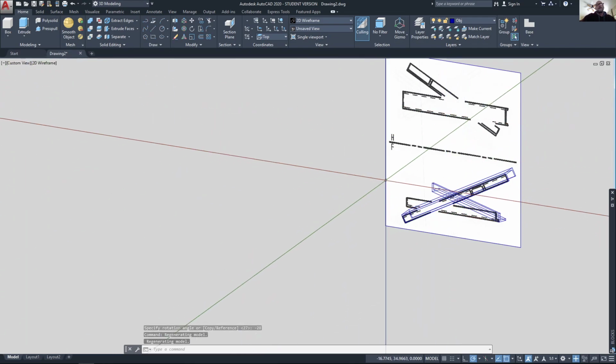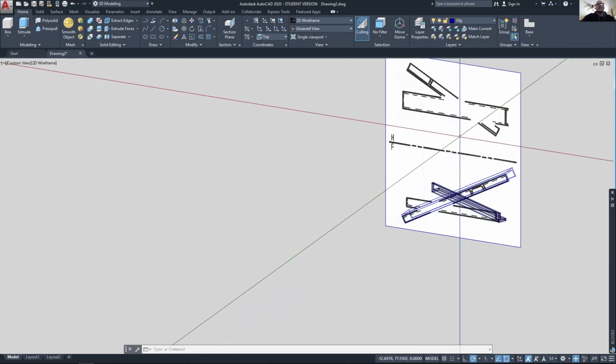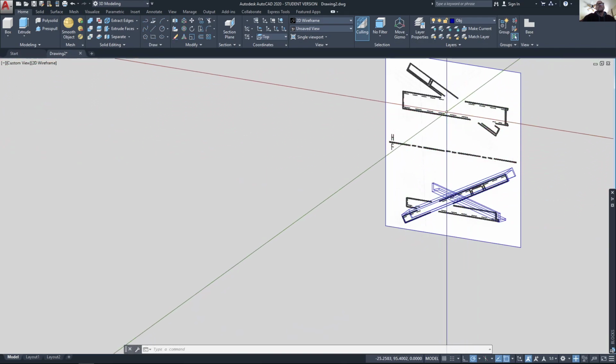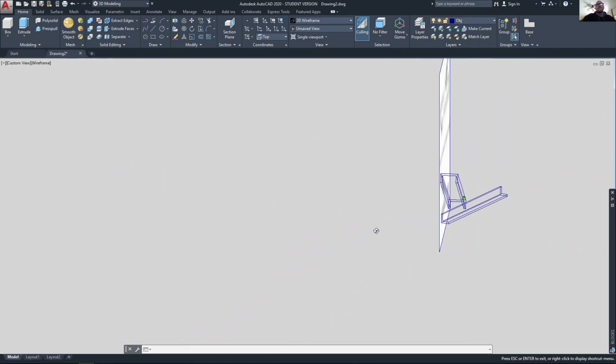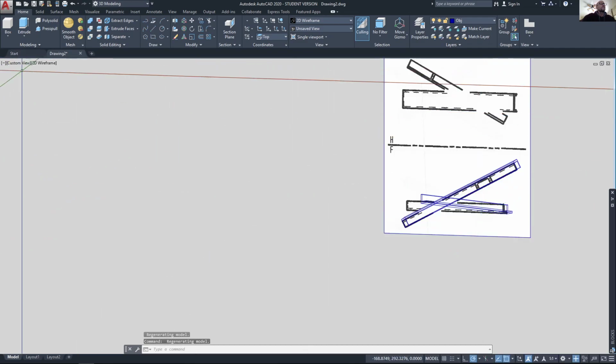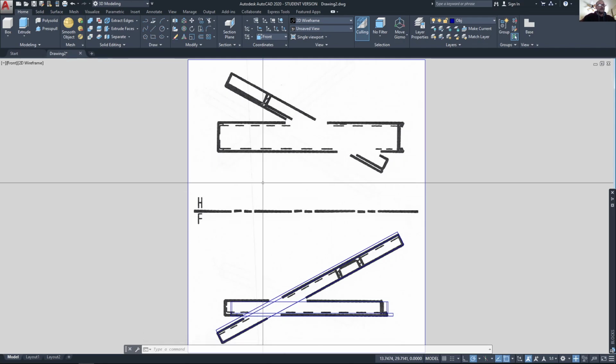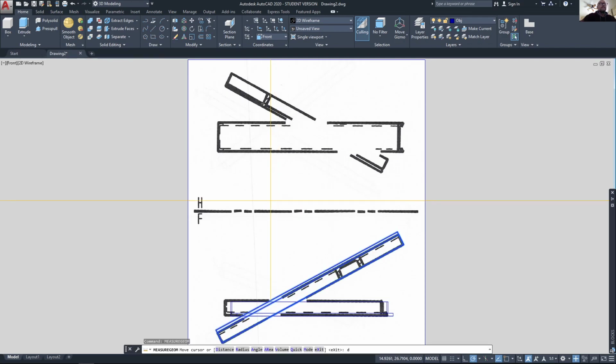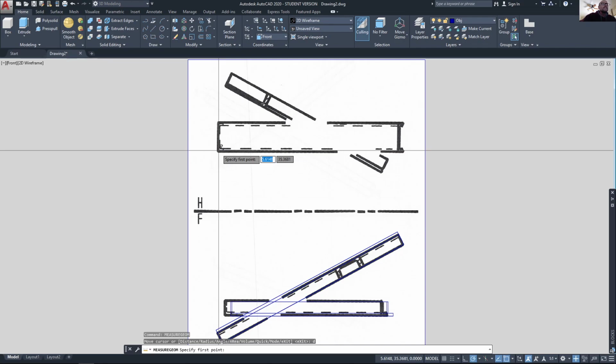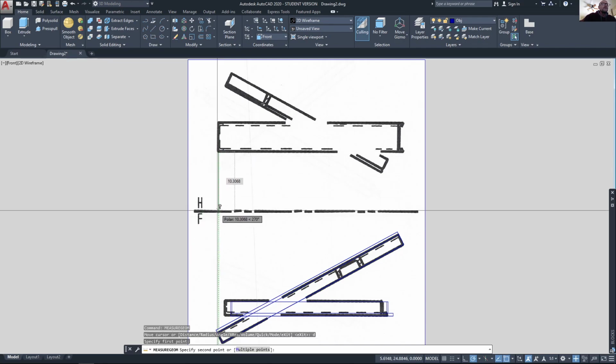Okay. So now I have these two pieces oriented by the front view. That's not a good look at it, but oriented in the front view and also in the top view, just not positioned in the top view because both of them are still resting along the edge of that plane. So all I have to do is measure, go back to the front view and measure their distance from the reference line, and then I should be able to move them. So I'll measure the geometry again, and I'll use the distance from this corner to the line.